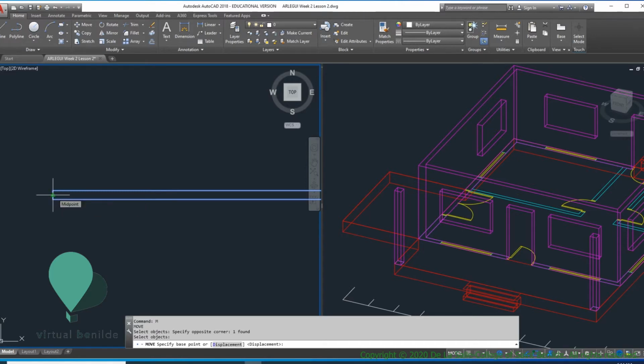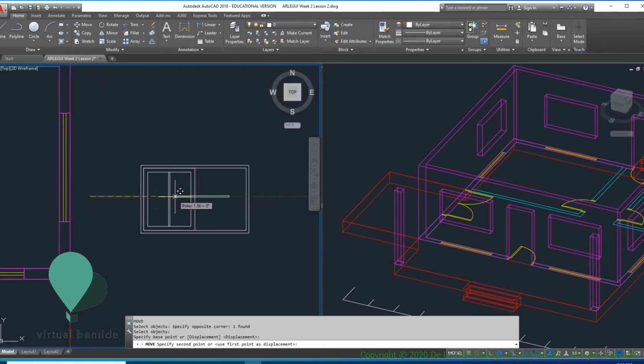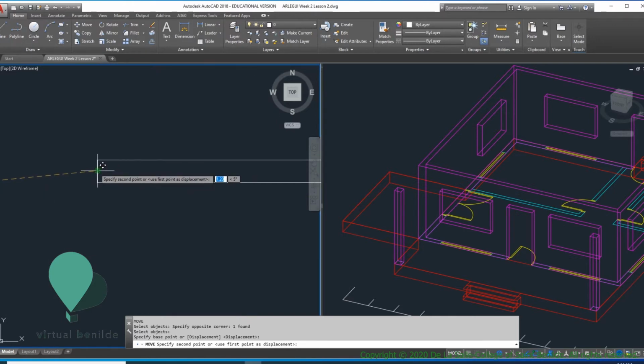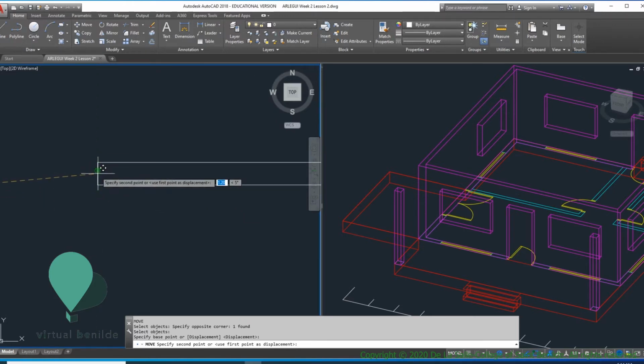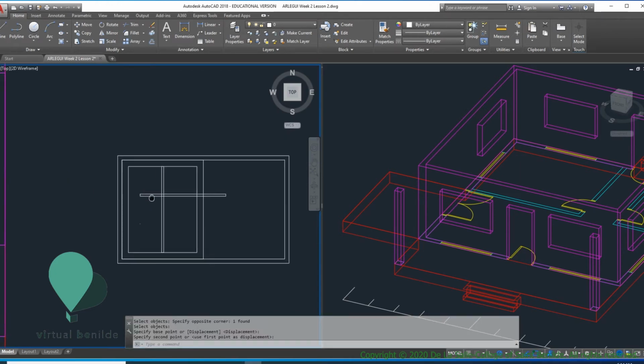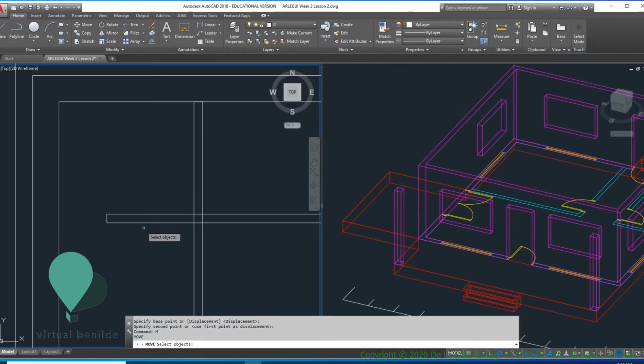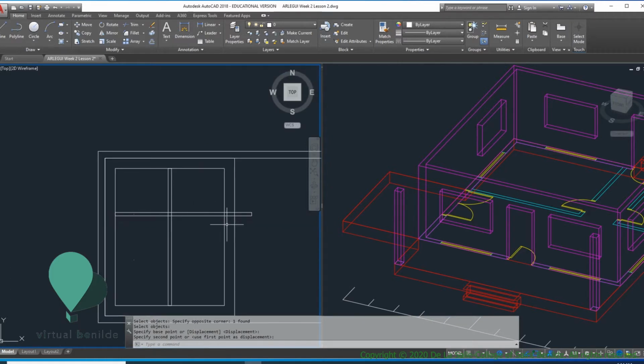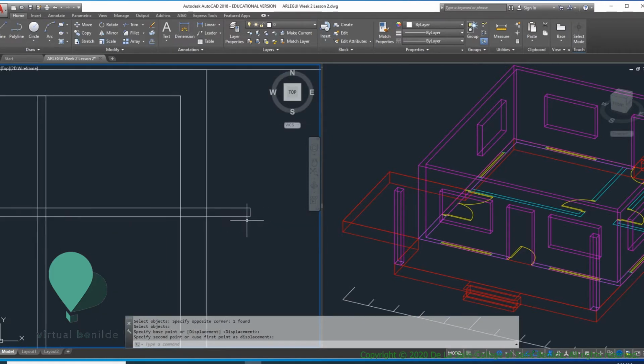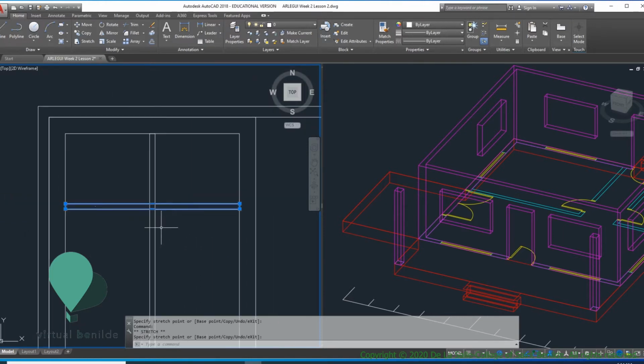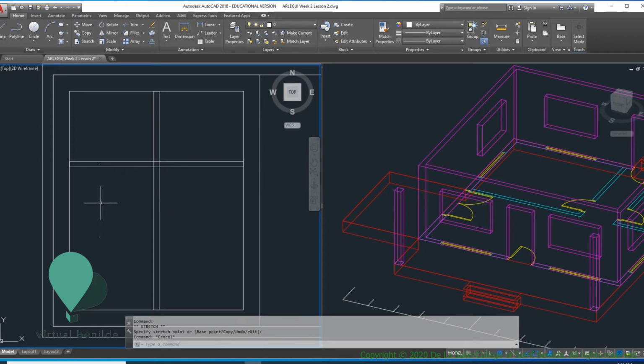So I'm going to click the midpoint of this, click as my pick point, and then node here. This is going to appear since we turned on the snap settings. There you go. And then another move, M, would be from that midpoint perpendicular. Now for this edge here, all I have to do is click onto this and drag the endpoints to snap onto those.